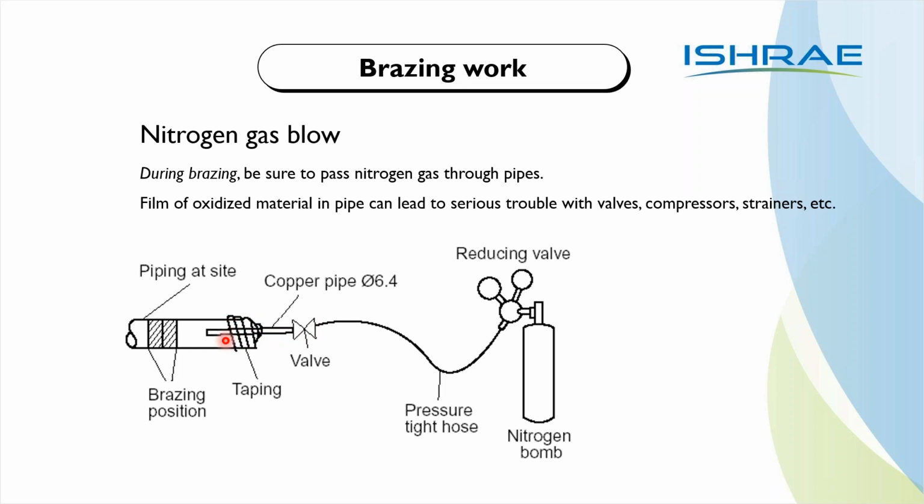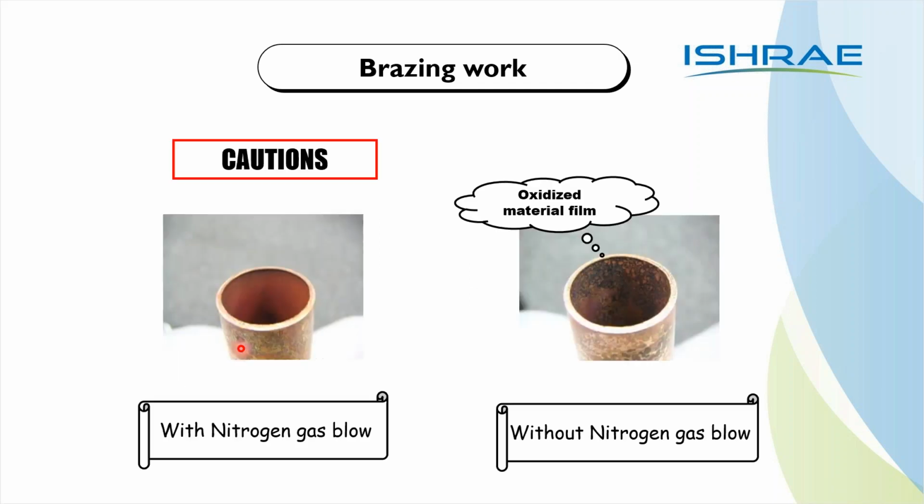This is very, very, very important for you, and you need to follow bleed off brazing, because as I had explained to you in my earlier presentation, your expansion valve has got 2000 steps. Look at the minute movement that your expansion valve does. Now, if you do not do this bleed off brazing, in the next slides, there's a picture which shows the carbon deposit. That carbon deposit can go and sit inside that expansion valve. So please do not compromise on this. Please do bleed off brazing only when you are doing VRF piping or VRF brazing.